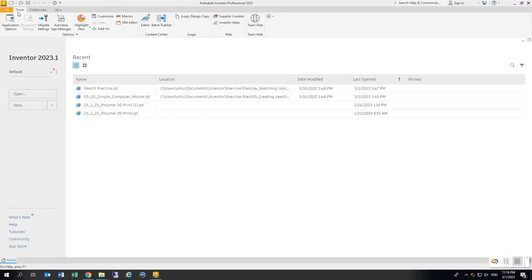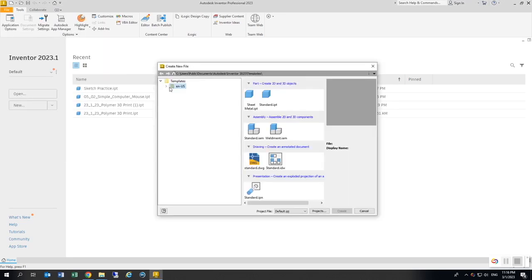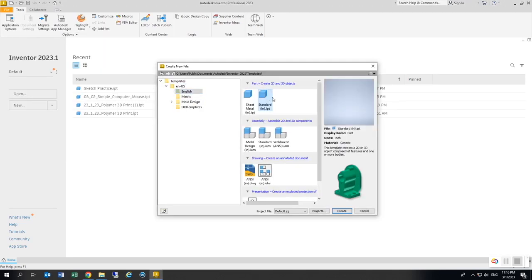Parts in Inventor are generally built by using different types of sketches. Think of the sketch plane as a surface on which we can sketch the 2D sections of the parts. The first sketch is usually drawn on one of the established default planes. Subsequent sketches or features can be created and added to the existing planar surface of the solid parts or default planes later. Let's first start a new part with inches as its unit.